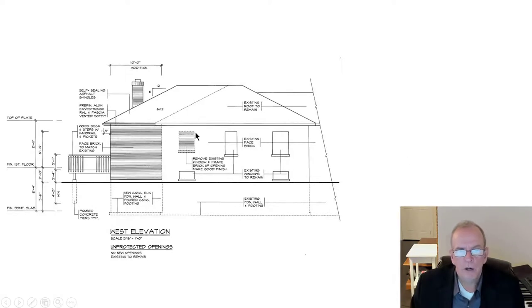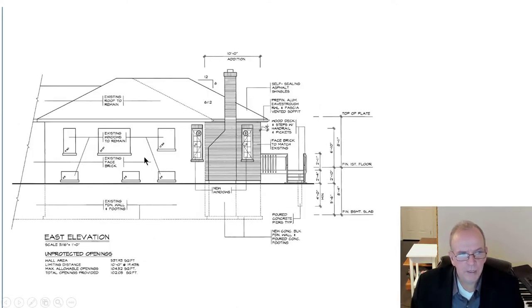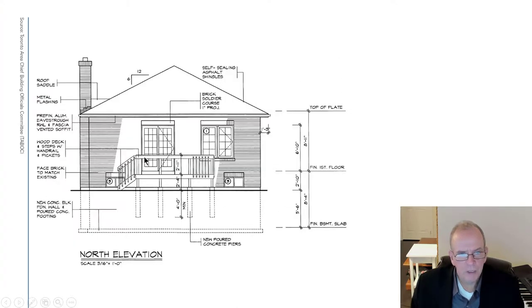I wouldn't do a concave joint where I join it up, because typically the old joint is worn out. It's a sand and lime mortar. So I would just cut it off and have it looking a little bit rustic. There are a few things that you can do to match that up that make it look better. It's the little things, right, in making a renovation flow and look like it belongs on the house. So there's the simple deck.